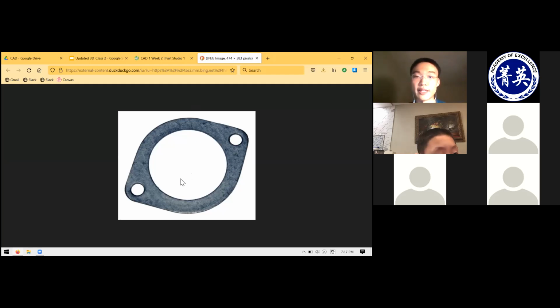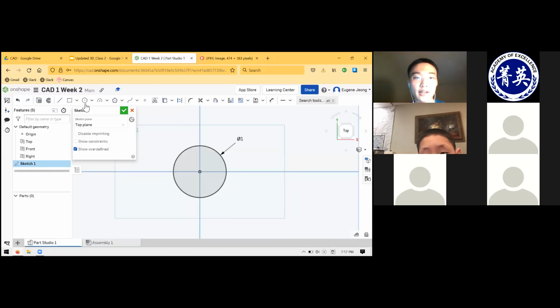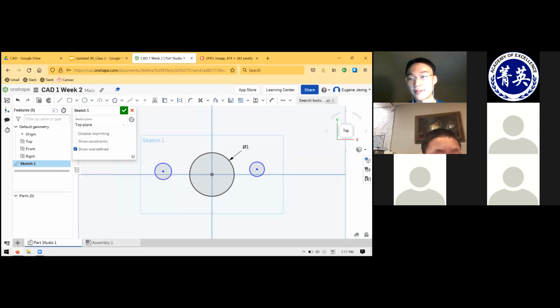So I'm going to make that first circle be this big hole in the middle, and then I'll add two more circles, again using the circle tool, off to the side. For the sake of demonstration, I intentionally put them not on the x-axis, but you can also just use the circle tool and draw them on the x-axis here. In any case, it'll become equivalent.